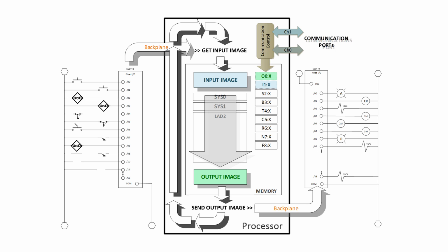Now there is a little sliver of time in there when it does housekeeping tasks and checks on certain parameters, does communications, because you can alter the state of these data table values directly from channel 0 and channel 1. So basically there's 4 phases, and we'll say it does the background or communication housekeeping task, then it gets the input image, reads the program, creates an output image, sends it out on the backplane, and then goes and repeats that again. Burn this picture into your head.